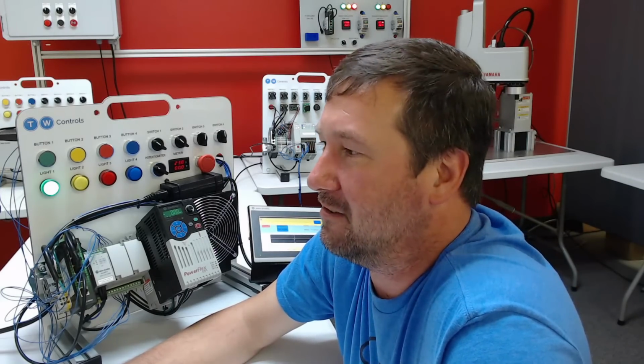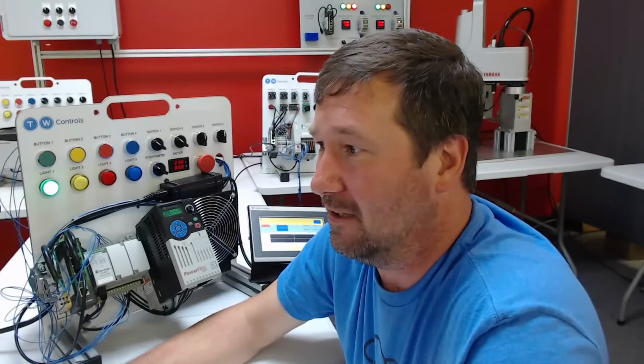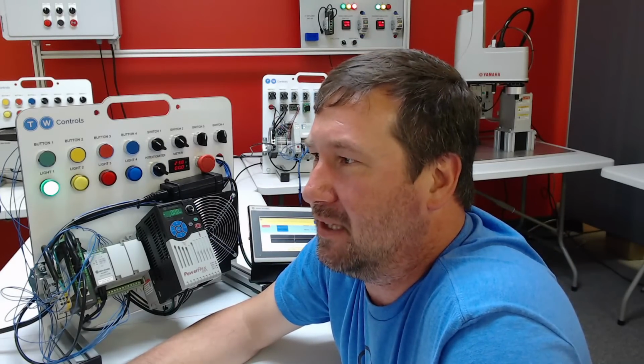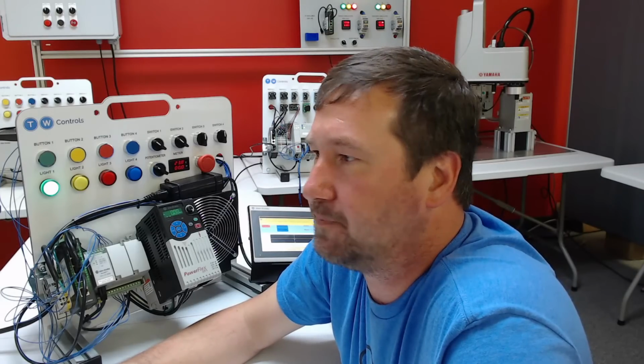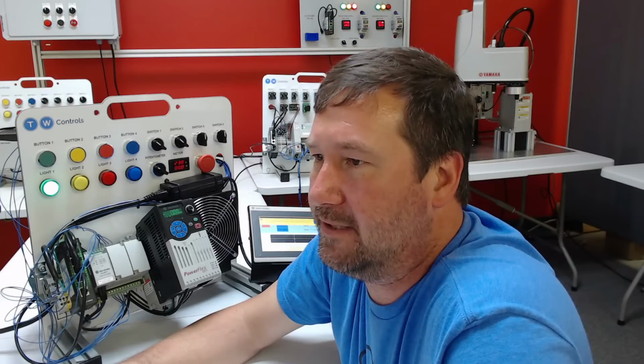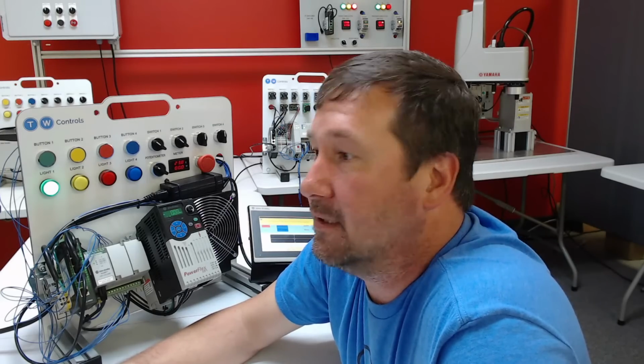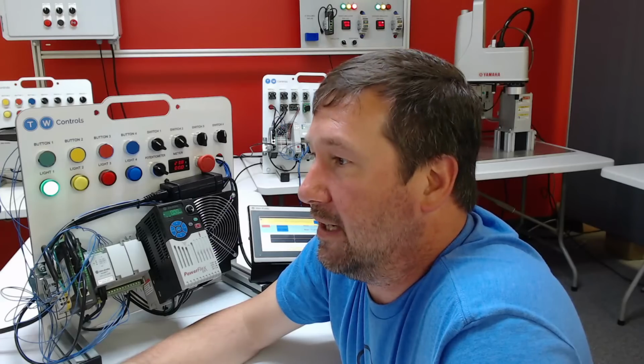So let's go ahead and put the timer in. I don't want to shortcut this one too much. Now, I got to tell you already, and you notice I didn't spend a lot of time on the ceiling, because after thinking about this, this is one that was brought up in the last live stream as an option, and I don't think this is a good option. But let's go through it and give it a fair shot. Right here, I forgot to put in the TON timer. So we'll drag that output energize, and then we'll bring down a TON.